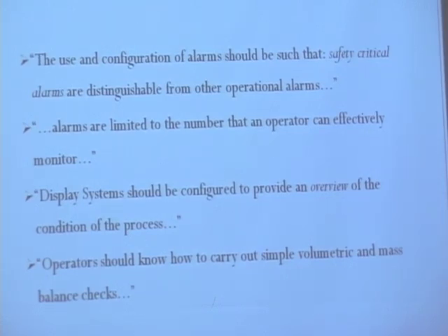So today, we have statistics from there that tell us the maximum number of alarms that an operator can manage. Basically, in normal operations, it says one every 10 seconds. And during an alarm flood, we shouldn't exceed more than 10 every 10 seconds. So we actually have some benchmarks now to measure ourselves against.